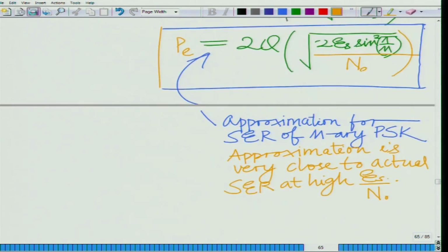Okay. So, that is pretty much what we have for M-ary PSK. We have seen the receiver design for M-ary PSK. In the previous module, we have seen the constellation and the waveform for M-ary PSK, and how to compute the average symbol energy. Now in this module, we have seen the receiver design, the matched filtering operation, and the optimal decision rule, which is nothing but the nearest neighbor decision rule, and we have also seen an interesting framework to compute the approximate probability of symbol error for any general constellation.